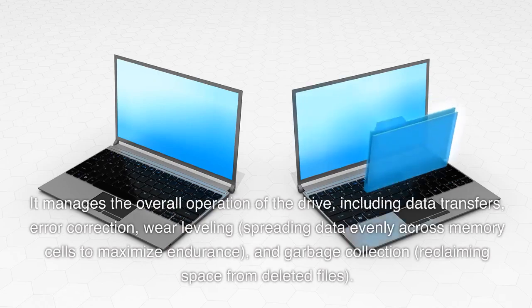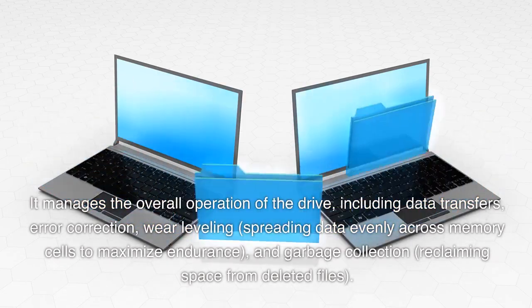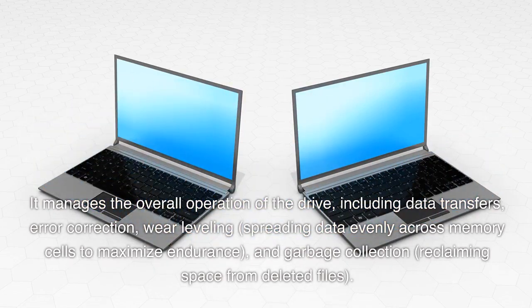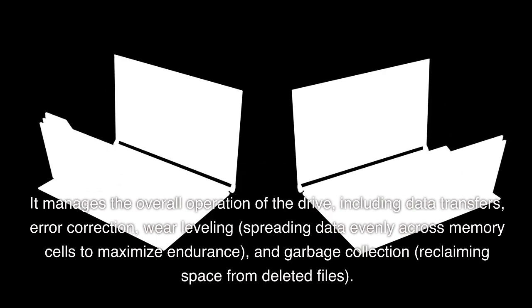Controller. The controller is the brain of an SSD. It manages the overall operation of the drive, including data transfers, error correction, wear leveling, spreading data evenly across memory cells to maximize endurance, and garbage collection, reclaiming space from deleted files.